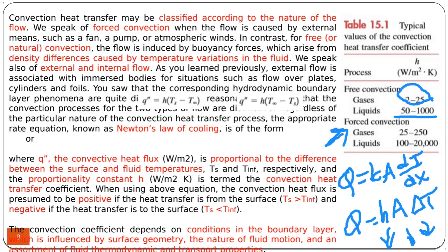So similarly, if the air adjacent to the radiator becomes hot and becomes less dense, it means colder air around will apply a buoyancy on it, right? So this buoyancy will cause this air to move up. So this motion of air will cause the convective flows. So this is how it's heating the whole room. It's very small, it's very far away from us, but yet we know that there's a very slow air motion inside this room because of the convection.